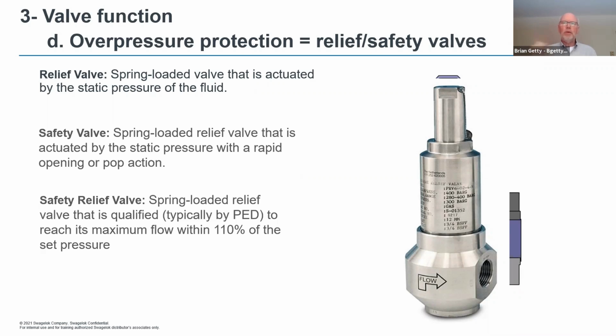And at that point, to reset it, it takes a technician that comes along. He has to push that handle back down to reset your safety relief valve. When you reset the safety relief valve, the idea there is that they've got a technician there to see what the problem is, why did this happen. All right, and they're designed to have somebody come by and reset it.